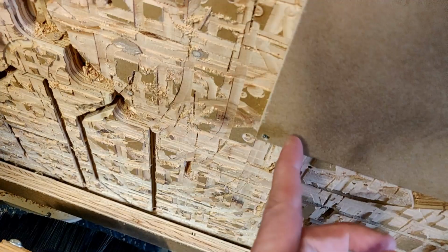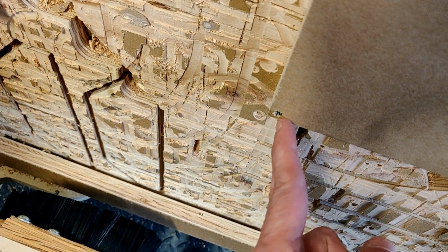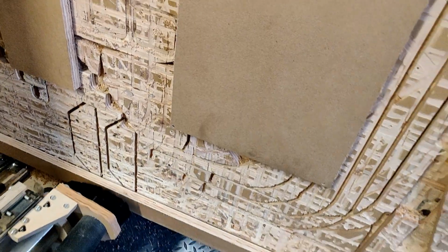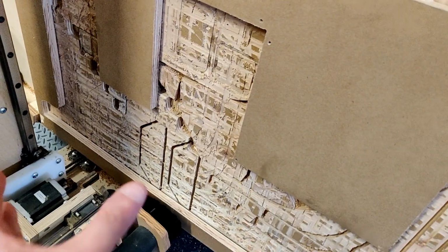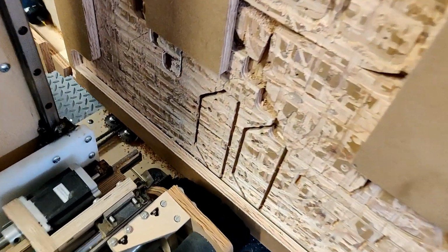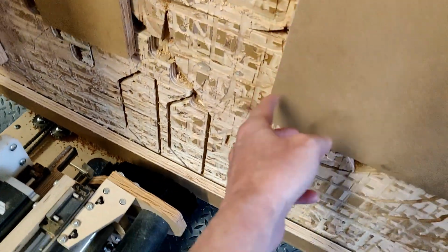And all I'm going to do is move that end mill just above the screw here. So we can also confirm that we're within our bounds using Mach 3. Okay, so I'm going to move this to this corner here. Okay, so I've moved the end mill in that location. See the end mill here. So it's just above the screw. I haven't zeroed out the DRO yet.